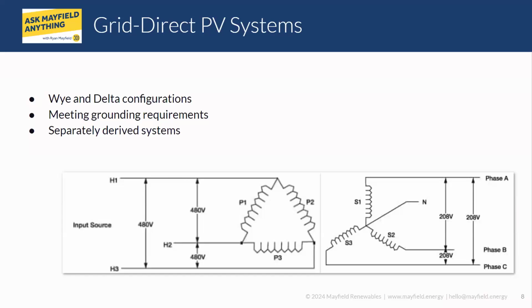We historically had seen, let's say 10 years ago or so, quite a few people that would regularly use autotransformers just to tweak the voltage on the output of some sort of inverter, which essentially functions, but you don't get the safety that you do with an isolation transformer. So we don't see that a whole lot these days. As far as the Delta and the Y and tying into the utility and the inverter side, Nick, can you express a little bit of what you've seen on that?